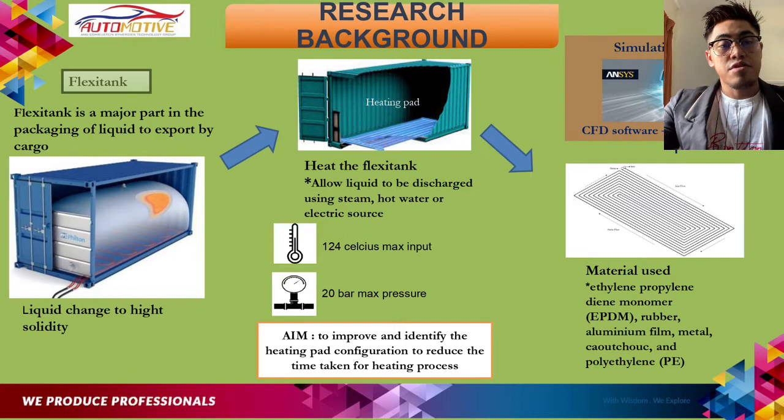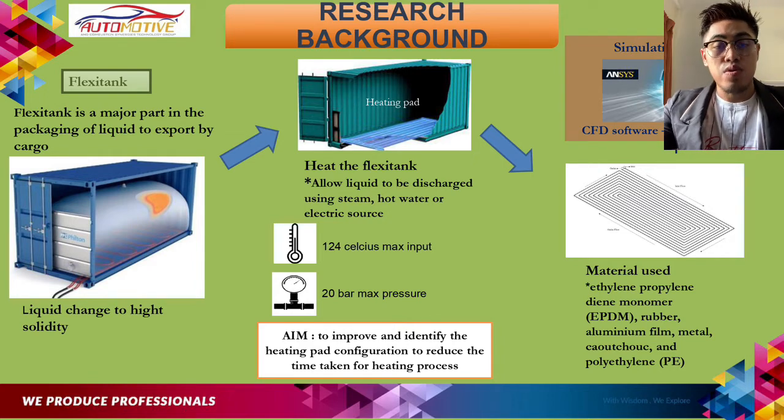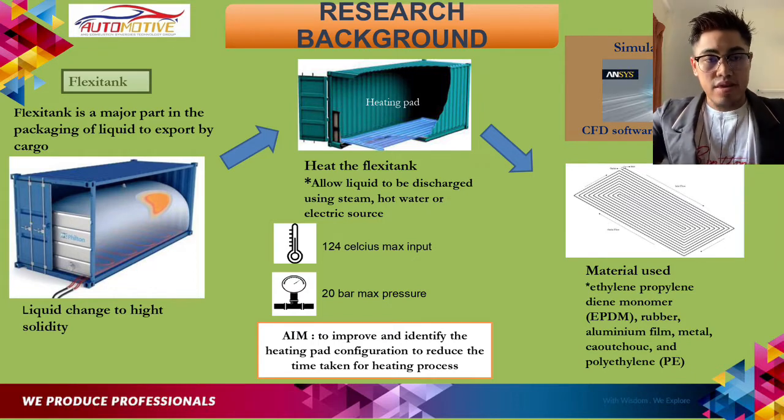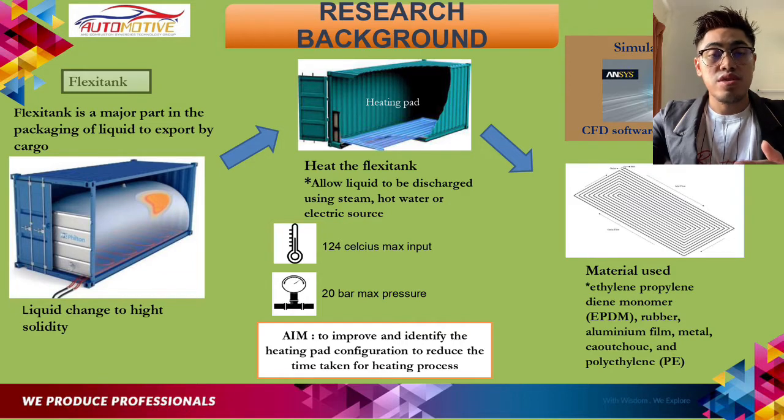So the main focus of the company about this process is the time taken. If the time taken for the heating process increases, it will increase the cost for transportation. For example, my Flexitank company takes about 48 hours or 2 days to complete the heating process. Therefore, the aim of this study is to improve and identify the heating pad configuration to reduce the time taken for the heating process. The result will be discussed on the thermal performance, thermal efficiency and heat distribution using CFD numerical